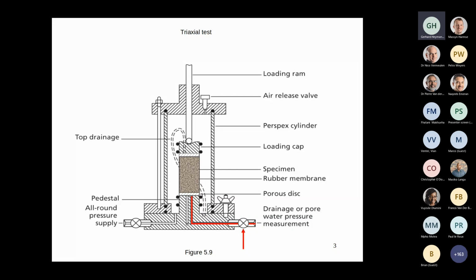So if you're one of the more senior engineers and you have specified in the past unconsolidated undrained triaxial tests for anything other than a fully saturated clay, that was a mistake. But we all learn through our mistakes. Now, maybe I'm not known for my diplomacy, so what I would say is, don't demonstrate your ignorance by taking a sample to a laboratory and asking for a UU test unless you are very sure that a UU test is the appropriate test.